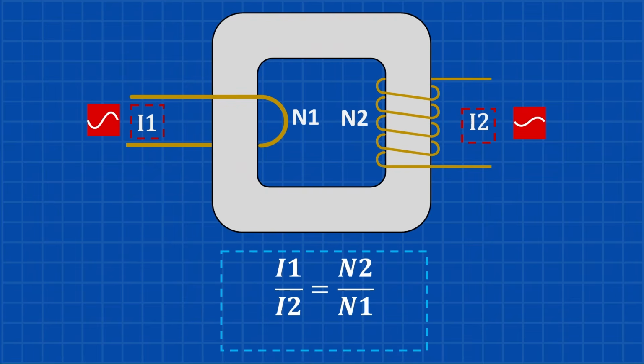This is magnetic induction. The relationship between them is based on the turns ratio. As the number of turns on the secondary increases, the current is stepped down proportionally. In most CTs, the primary is just one turn, the wire itself, which allows high current to be safely reduced to a lower, measurable value.